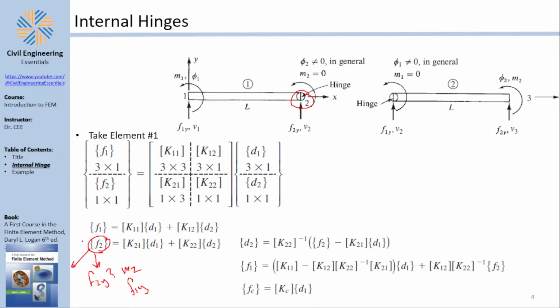So it might be confusing, and it truly is, but I'm trying to explain that at least for the purposes of this derivation, 1 means unreleased and 2 means released, according to Darryl Logan's book. So F2, because those are released, should be 0. It becomes really crazy and hard when you get to the plastic hinge domain because then F2 is not 0, but this is something advanced. F2 here is 0 because it's released.